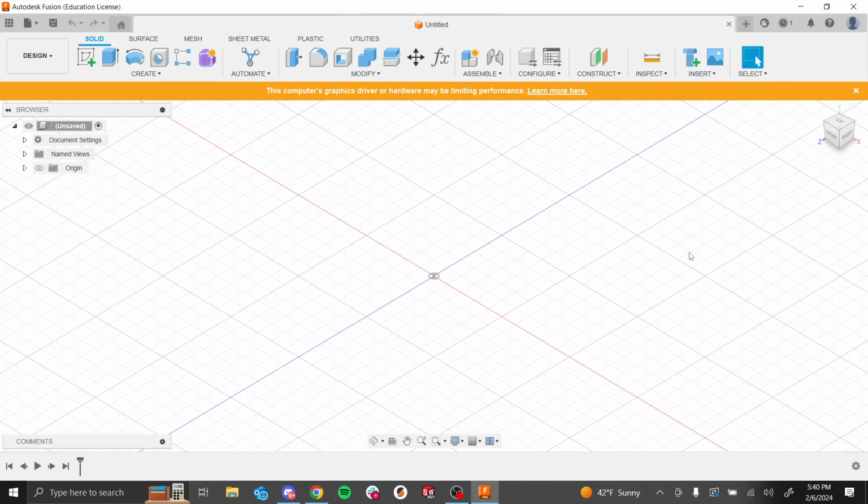Whenever you design something, you might want to use something that already exists as a reference, right? What a lot of people would want to do is take a photo of something and then reference it in the CAD. And the good thing is we can do that. We're going to use something called a canvas, and the canvas will allow us to insert images into our design.